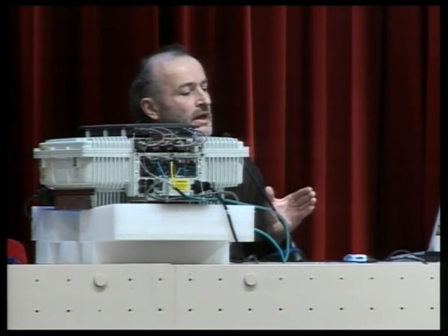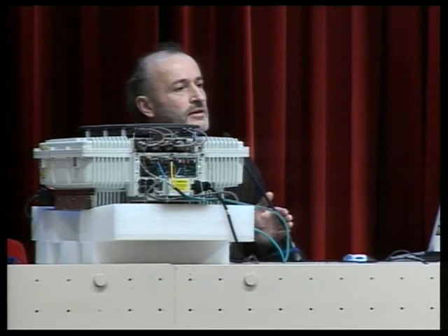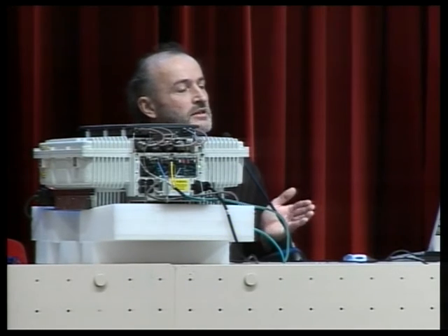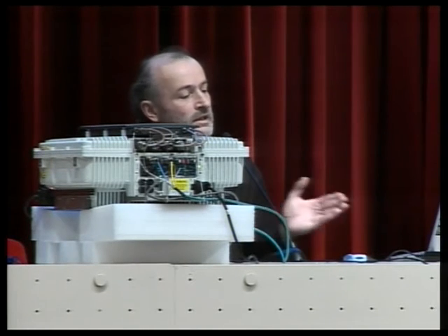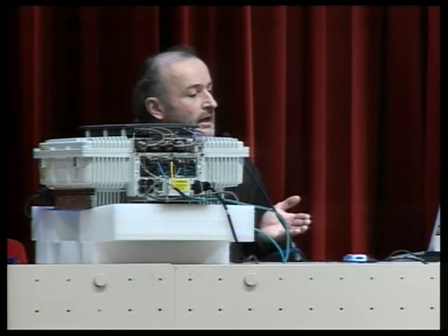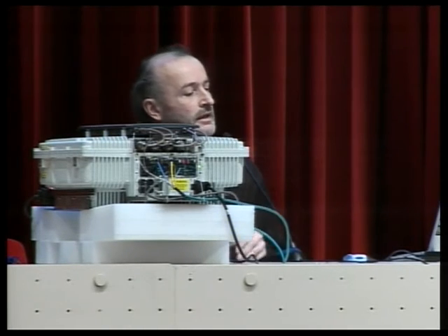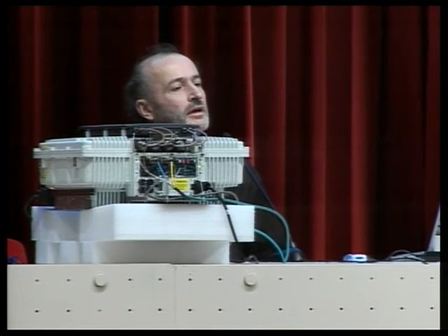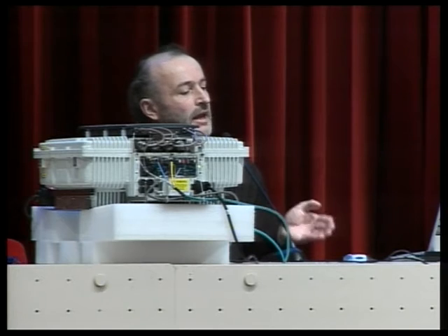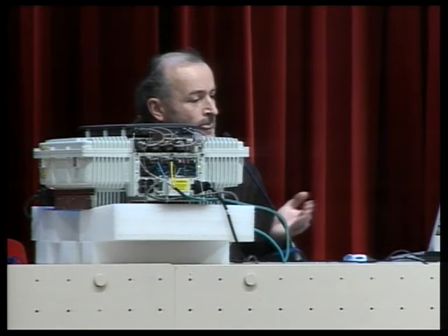And those TRAU packages contain a header which allows to synchronize them. This header is a specific bit pattern which is only used in the header, and so it can be easily detected. Basically, this adds some overhead, but the overhead is not too large. We start with 13 kilobits per second, which we get from the GSM decoder, and we end with 16 kilobit after putting them in those TRAU frames.